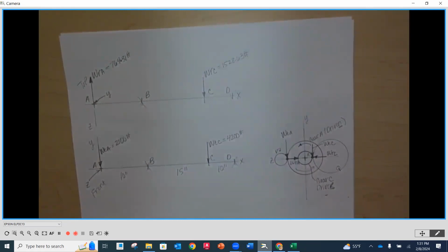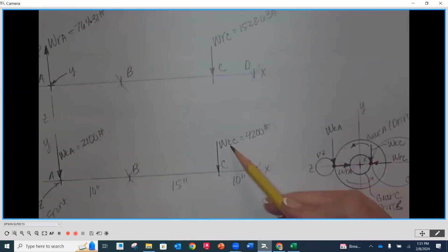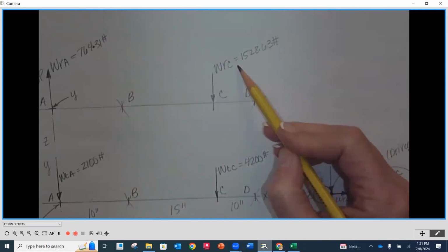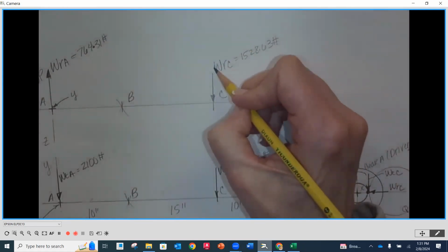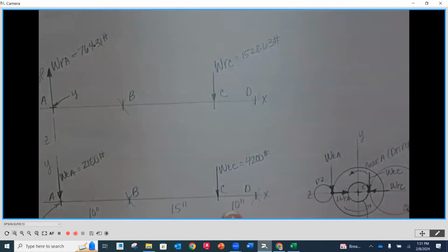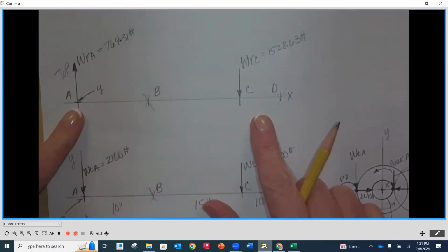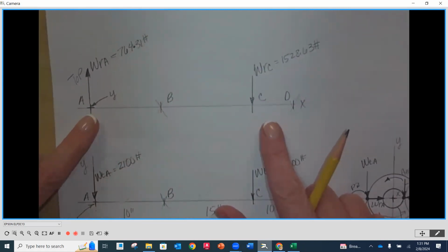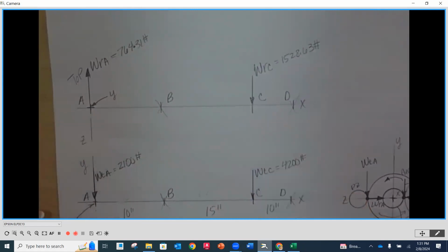It's fun. Which one? This is tangential and this one's radial. Sorry, I know it's not that easy to read up here. So tangential is in the front view for both of these. That's not always the case, I'm going to tell you that. These just happen to work out this way. And then up on top are radials for both.